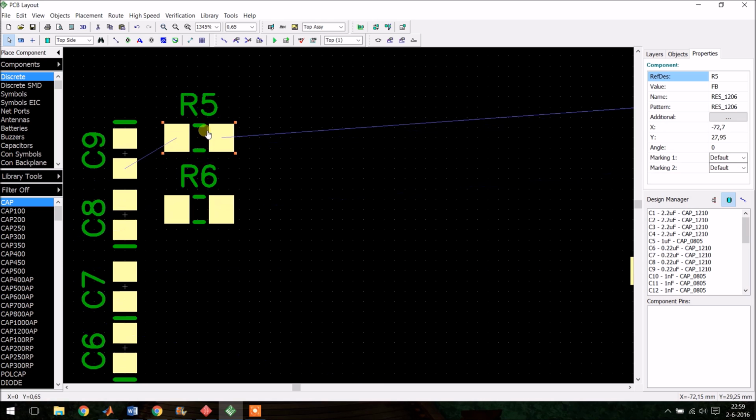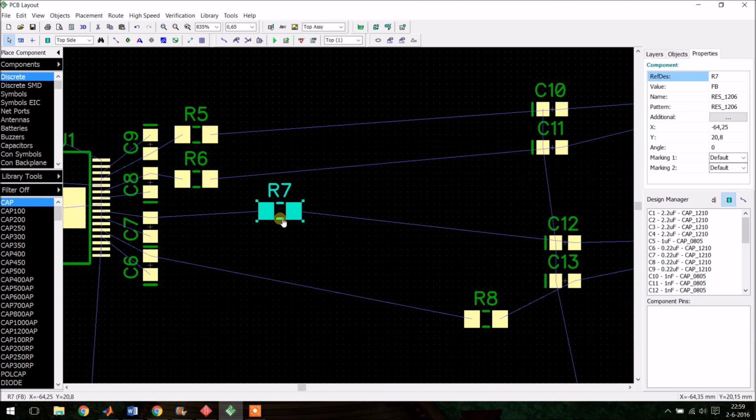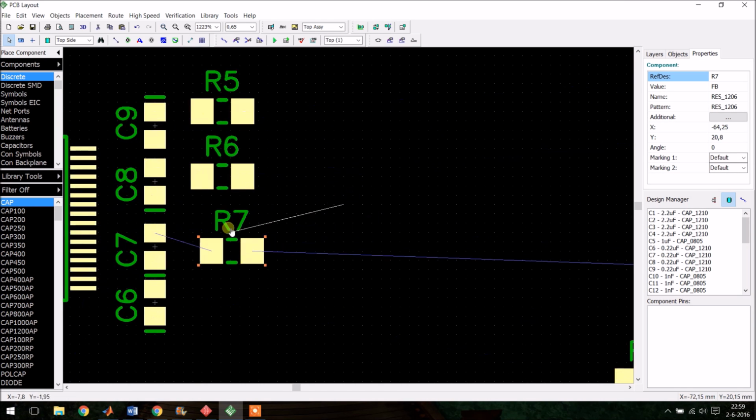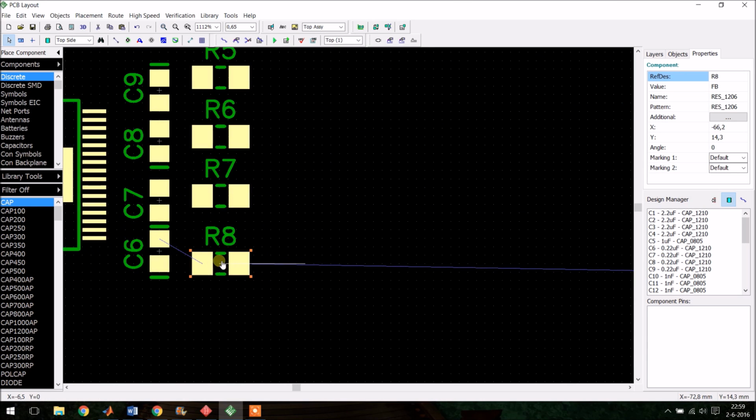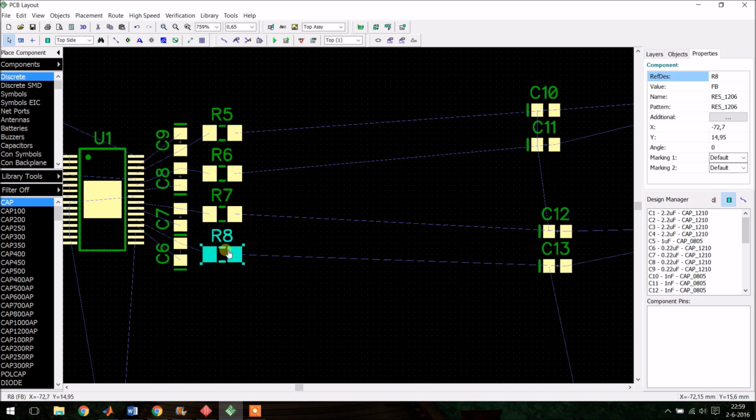It's almost impossible to get the place just right in the first try. You have to move them around after you've placed them. If you want to recheck if there are shorter connections possible to the pins, you have to press F12. Yes, F12.